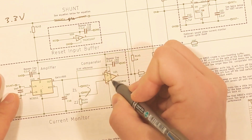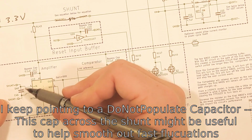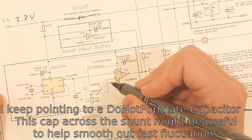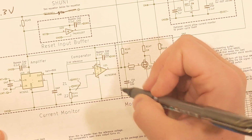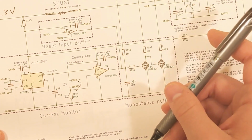And based on that reference voltage, I check to see if this gets too big. If there's too much current flowing through this resistor, this will just get bigger. So if this voltage gets too big, it'll end up going over the threshold. It'll cause this op amp to pull low.